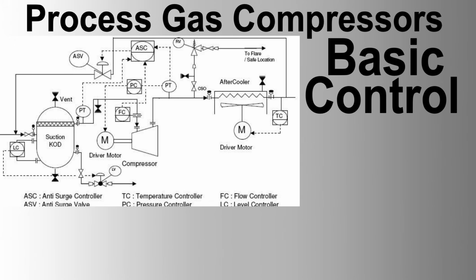Installation and design considerations. 1. Accuracy. Pressure and flow measurements must be accurate to ensure the compressors operate within safe and efficient ranges. High-precision instrumentation is used for monitoring and control. 2. Material selection. For sour service, presence of H2S, materials resistant to sulfide stress cracking and corrosion are selected. Common materials include stainless steels and nickel-based alloys.